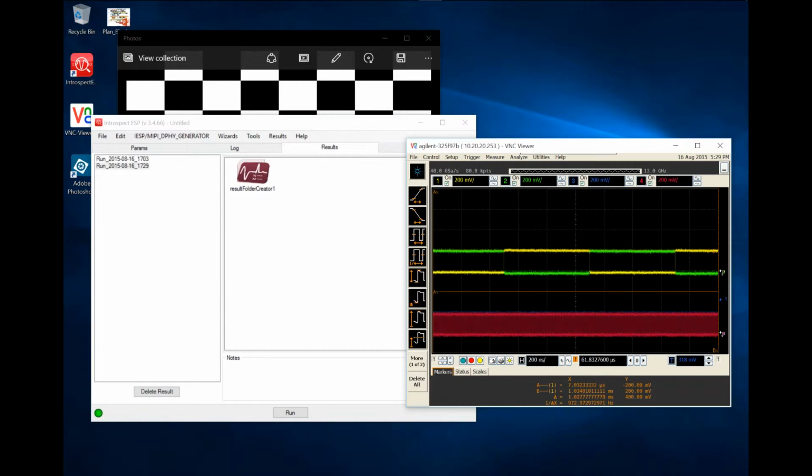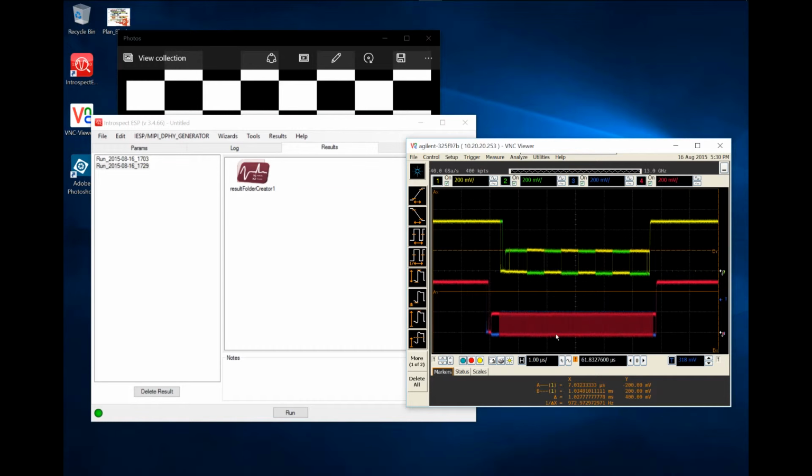we have been connected to the oscilloscope, as I mentioned, and we're seeing now how the pattern looks like on the scope. And if you recall, the bytes that I entered were very simple. They're 0 or 255, which really means all zeros or all ones. And so if we look at the positive terminal of the lane here, it's alternating between all zeros and all ones. Just zoom out just a little to see a view of the packet. So that's the entire packet representing the checkerboard pattern.